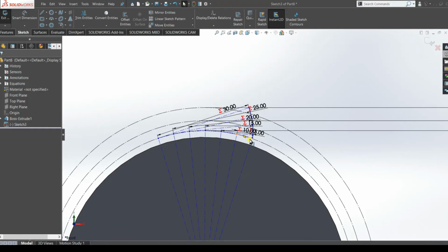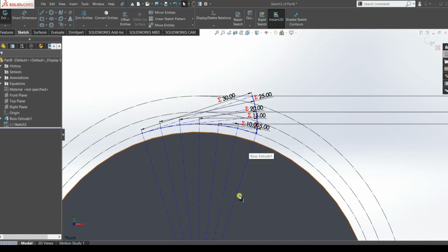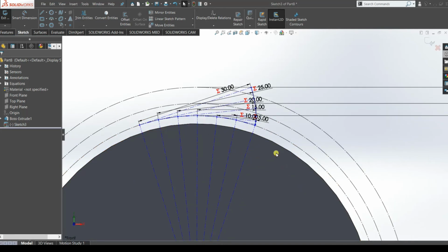So we will be using the same principle and we will find the angle for the pi arc length. Now it is very simple to find the theta if arc length and radius are given. Radius is equal to 50 mm, which is the half of the pitch diameter, and s, which is equal to pi. Now we know the relation s is equal to r theta. Now we will put the values. Pi is equal to 50 multiplied by theta, so theta is pi over 50. Now this angle is in radians. We will convert it into degrees by multiplying it with 180 by pi degrees. So it will be 3.6 degrees.